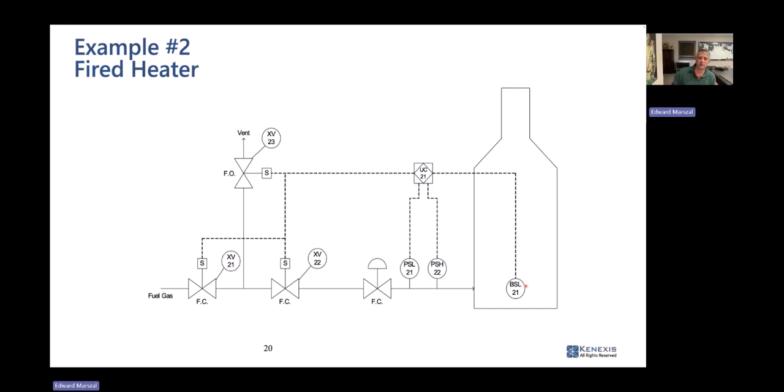So what you need to do is unhook the hazard a little bit and look at the causes to determine, well, what interlocks, what SIS functionality is going to be able to detect this cause, and make sure to define it as that cause to consequence scenario. What equipment from my safety instrumented system sits in this cause to consequence scenario? I need to define that as a safety instrumented function.